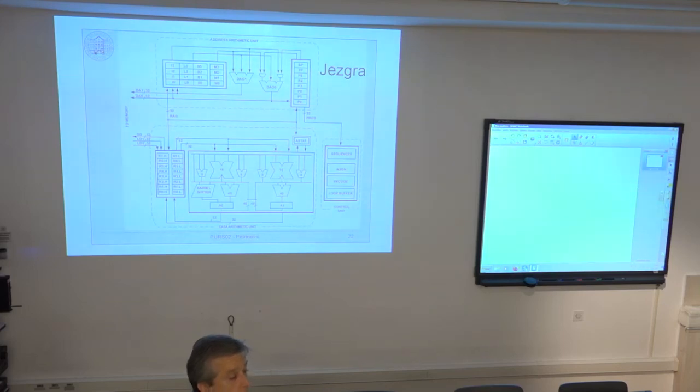In this case, they wanted to avoid this restriction because it complicates the linker part of the high-level compilation, and to avoid these problems, how to do this efficient linking, they decided, okay, we will have a separate base register. So this B is the register that contains the first address of the buffer. Okay? And then this I is always relative to this B, but modulo L.